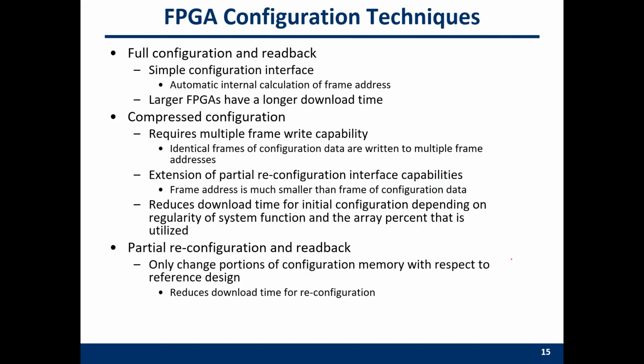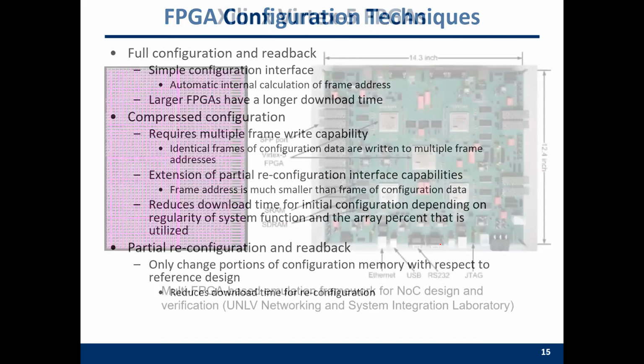So some FPGAs also support partial reconfiguration and readback. You only change a part of the configuration memory based on your design needs. So in this way, you can reduce the download time and reconfiguration time.